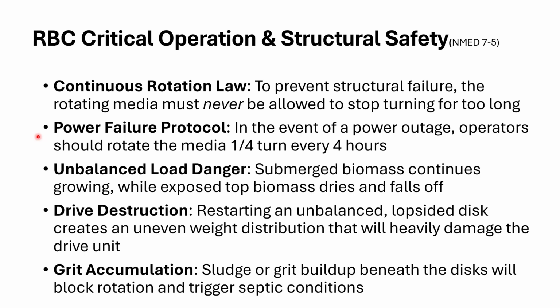And here's another pretty big one. If we have a power failure, every 4 hours you want an operator to go in there and turn that barrel a quarter turn. You want to do that to make sure, one, the structural integrity is okay, we're not going to have those bearings fail, and that weight is not going to cause bearing or structural problems.